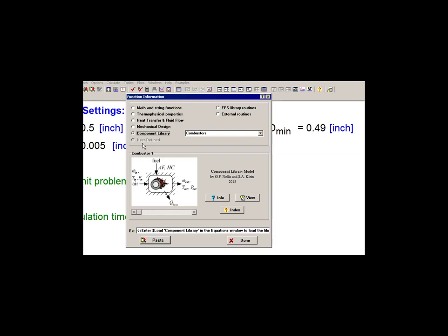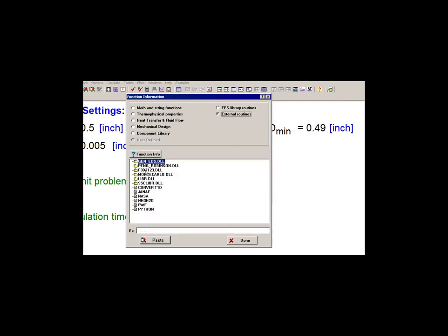A very powerful feature of these is that functions and procedures can be written in any compiled language, like Pascal or C or Fortran, and then these code segments, which are referred to as external functions and procedures, can be used in exactly the same manner as internal built-in EES functions and procedures. They can be coded so that units can be checked, just like internal functions, and warning and error messages can be returned.